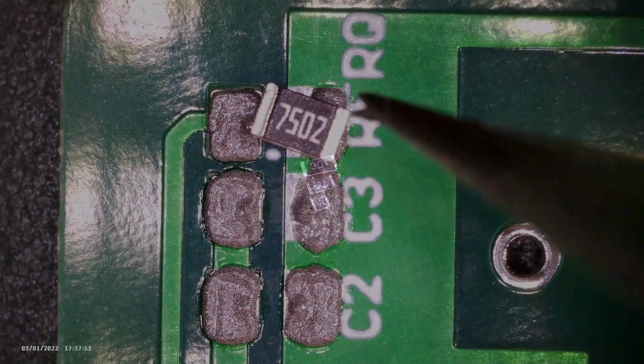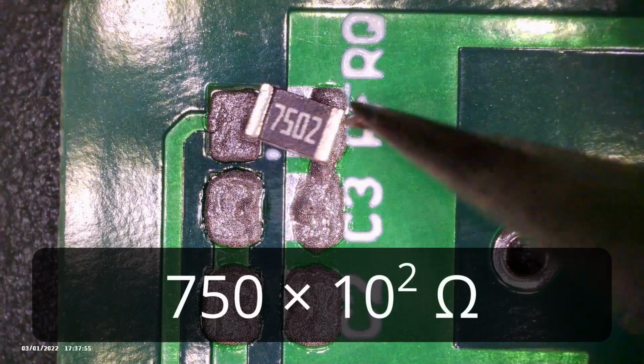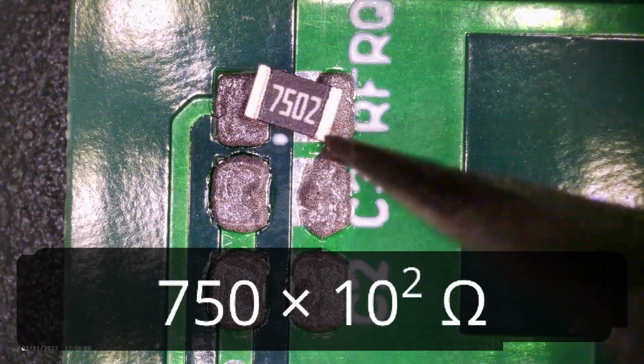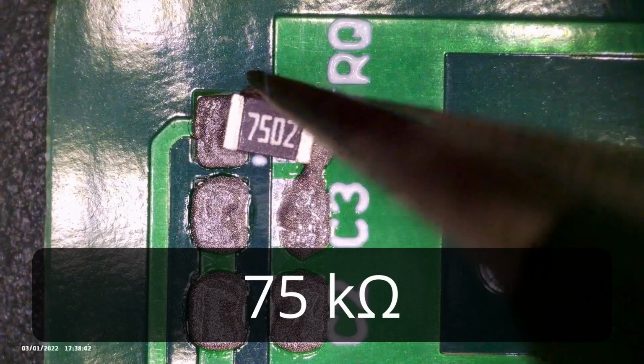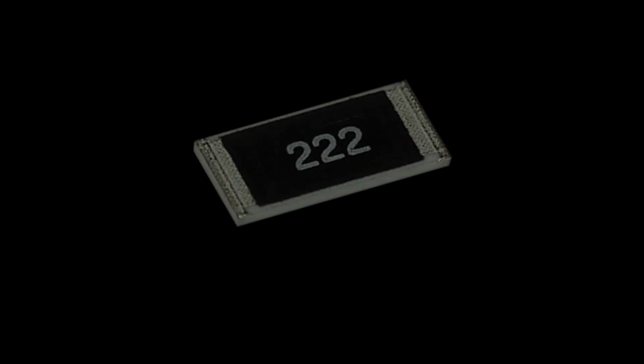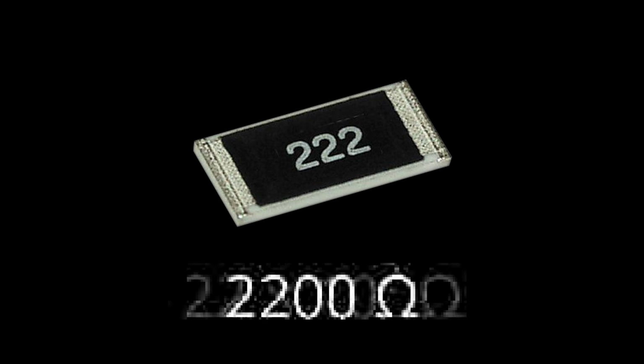Moving on to the surface mount versions, things get a little easier to understand, if not easier to actually read. Most SMD resistors will have the value printed directly on them in the format of 3 or 4 digits, with the last one being the power of 10 multiplier and the other digits being numerical values. Sometimes they'll add an R into the mix, which acts as a decimal point. So a 2R2 resistor is 2.2 ohms, and a 222 resistor is 2200 ohms.